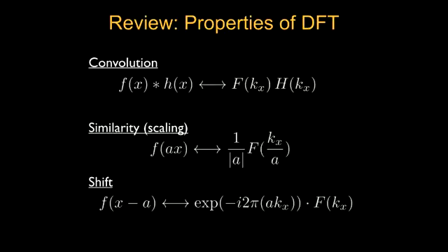If you squeeze it, you have to stretch it in the Fourier domain. And shifting: whenever you have a shift in one direction in the time domain, then in the frequency domain there will be a linear phase included. So whenever there is a linear phase, there will be a shift, and whenever there is a shift, there is a linear phase. This is a very important thing.